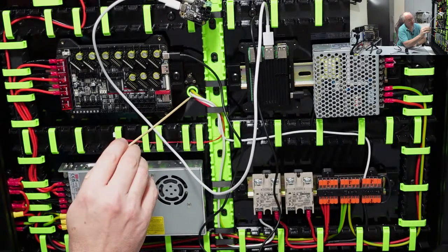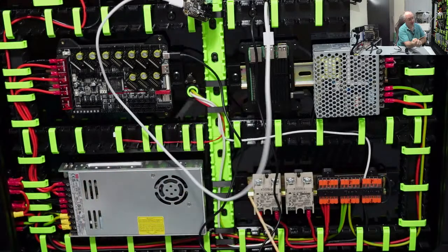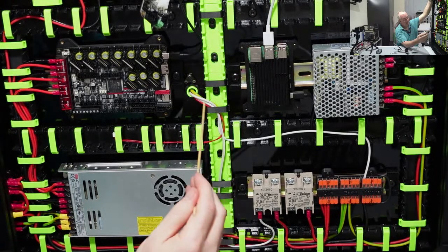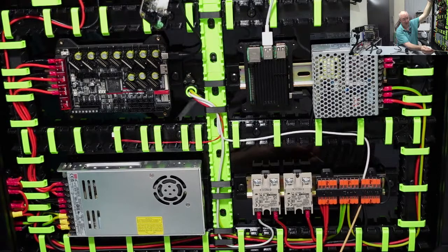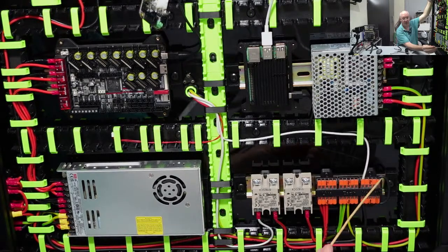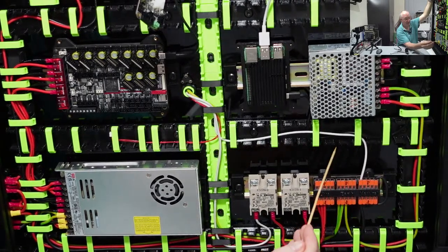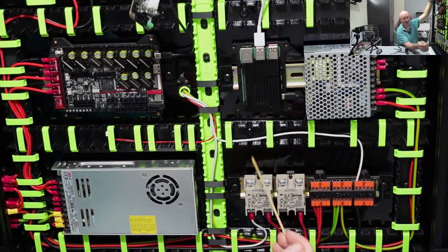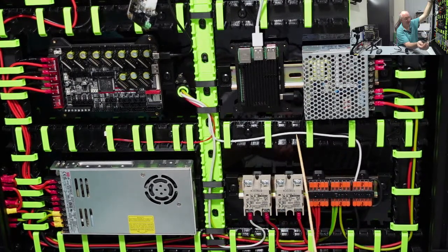The next thing is I've got the two bed heater wires coming in. One is just a little bit in the way, I'm going to lift that up. One's going in and going to my neutral, right, because it's an AC bed, so it needs to go to the neutral. This neutral's coming up, it's got a bridge going up like that just to get to this set of Wago connectors. The reason why I had to go this way and not down the bottom is this wire is just not long enough to get to it from the bottom, which is a bit unfortunate, but that's just the way it is.